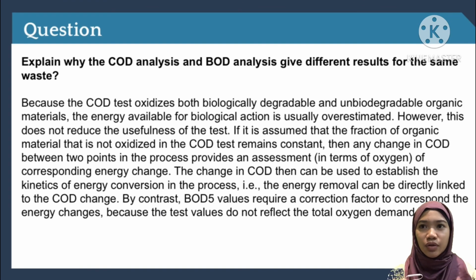The change in COD can then be used to establish the kinetics of energy conversion in the process. For example, the energy removal can be directly linked to the COD change. By contrast, the BOD value requires a correction factor to correspond to energy change because the test value does not reflect the total oxygen demand.